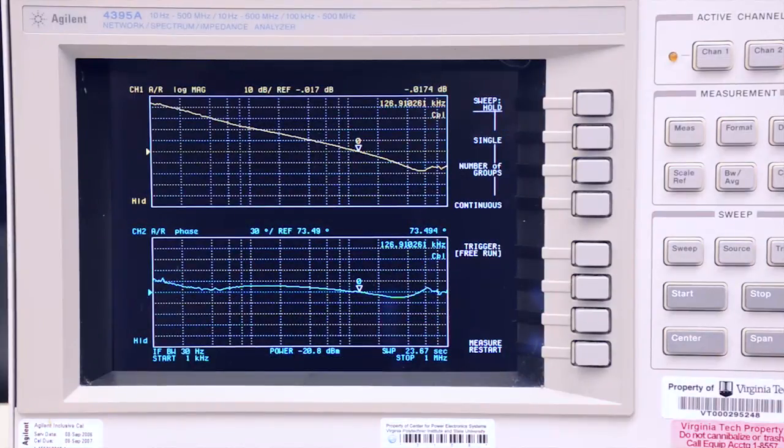Let's see the small signal property of the hybrid interleaving structure. The major loop gain of the controller shows this structure enables high bandwidth design over 120 kHz. The benefit of high bandwidth design shows in the reduction of output cap.